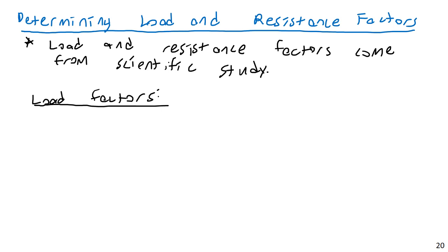What you might do is go out and survey thousands of classrooms at random times and ask how often the actual live load, in other words, the total combined weight of all of the students, the teacher, the desks, the chairs, the tables, all that kind of stuff, maybe even interior wall partitions, is more than our assumed load, and by how much?